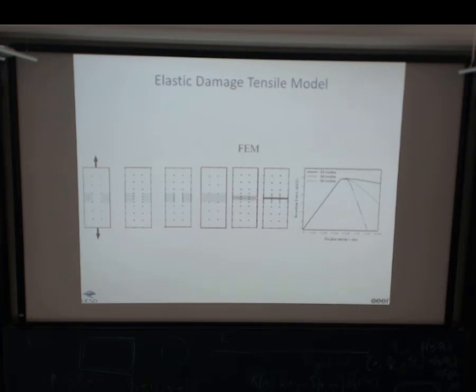Refine the mesh, you will localize into here. We further refine the mesh, localize into here. And you get a completely different solution. Solution never converges. In fact, you keep refining it, this curve will curve back. So never converge. So you've got to do something about it.